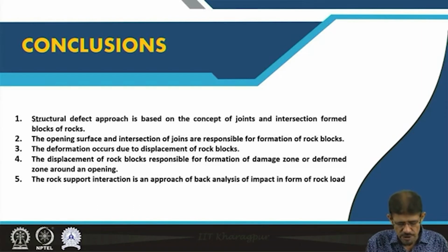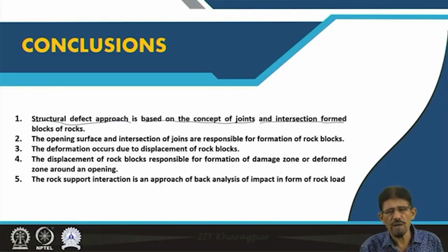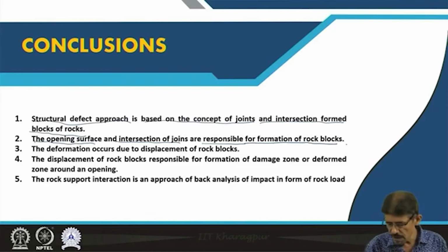As far as the structural defect approach is concerned, it is based on the concept of joints and the intersection of joints along with the joint opening surface, which are responsible for the formation of blocks of rock, where these blocks should be rigid in nature and the joint sets should be more than one. The opening surface and the interaction of joints are responsible for the formation of rock blocks, and the movement, deformation and deterioration take place due to movement of the rock. The deformation occurs due to displacement of the rock blocks.